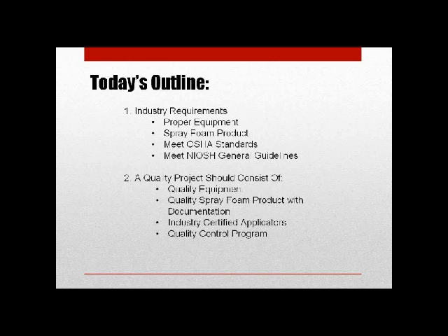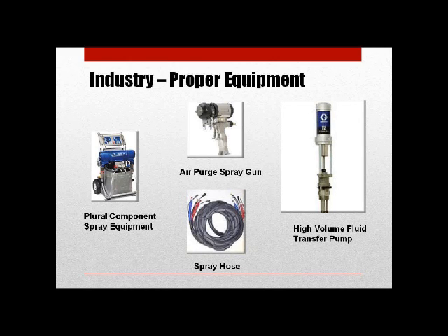Thank you, John. First thing we want to go over within the industry requirements is, of course, to have the proper equipment. Here we have the minimum equipment that you need to spray a quality spray foam project. On the right-hand side, we have the fluid transfer pump. This pump supplies the spray machine with material from 55-gallon drums via a 3/4 to 1 inch supply hose.